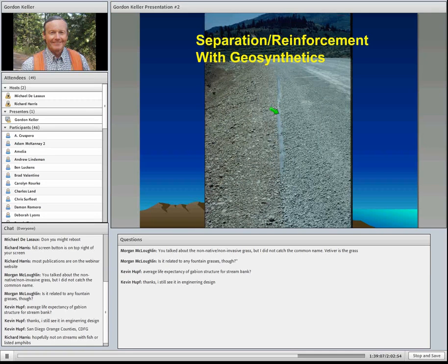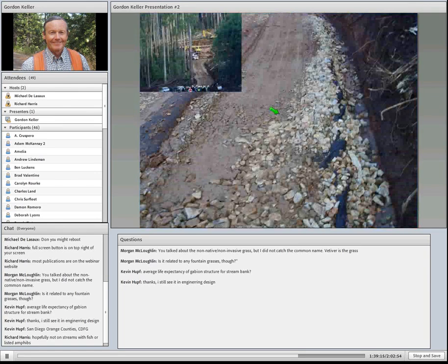Here, for instance, this was on a main road. Here, for instance, it was floated. This is geosynthetic over just a local soft area. It was the access road going up into a log landing. Just a local spring area. So rather than dumping in nothing but a lot of rock, they put down a layer of geotextile, put in rock, and then it just takes less rock and it doesn't just disappear down into the mud. In this photo, it's ready for a little bit more rock and started to heave up here in the middle, but it can save you a lot of aggregate.